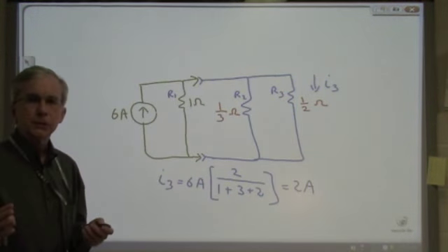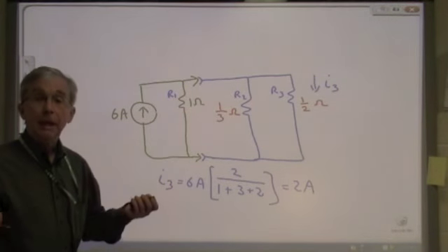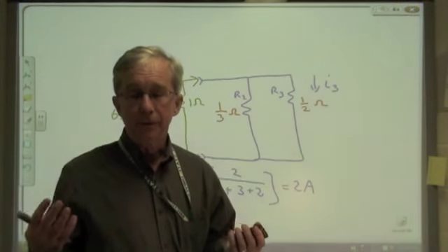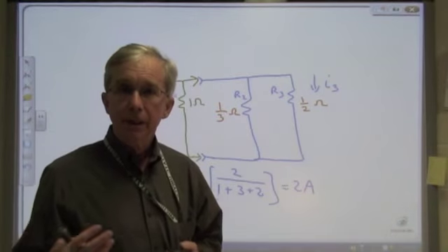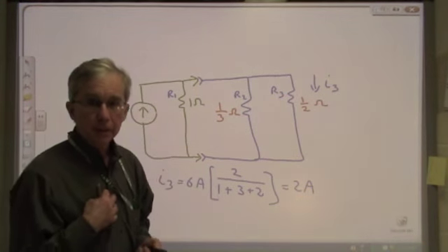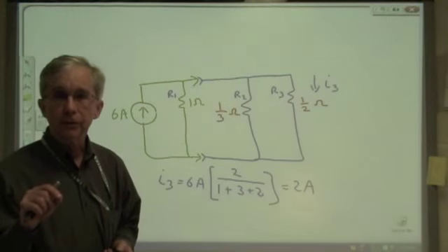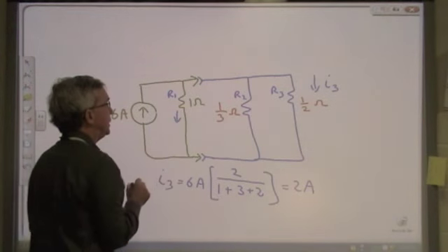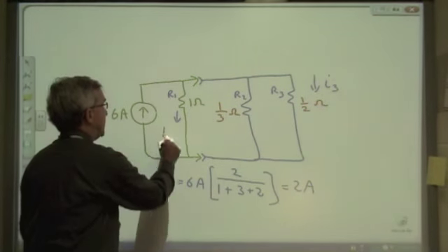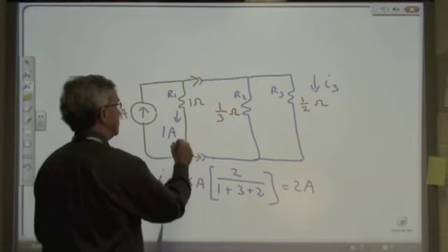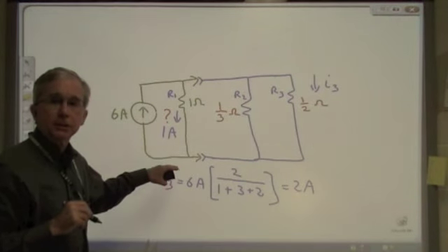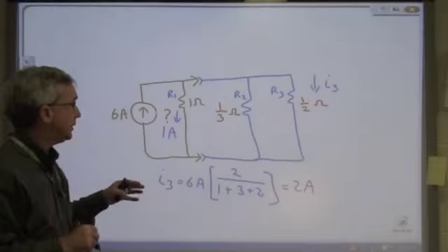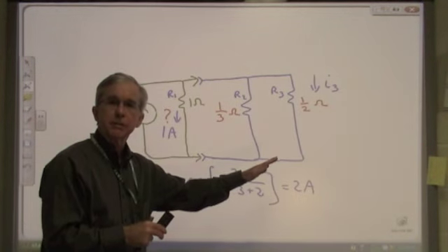So here we have solved the circuit by simplification and by using current division. Earlier we talked about a pitfall with voltage division that we wanted to avoid. Here I'd like to show you another pitfall to avoid. Suppose that we had instead wanted to find the current through the resistor R1. Can I say, oh, the current through this resistor R1 is 1/6 of 6 amps, or 1 amp? I'm going to put a big question mark beside that. This is the part of the circuit that was transformed. Its currents and voltages will have changed. The circuit was equivalent only from the rest of the circuit's point of view.